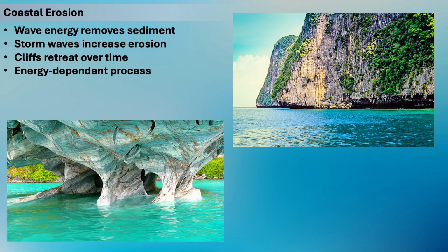Storm waves are especially important. During storms, wave height and period increase. Longer period waves carry more energy and penetrate deeper into shallow water before breaking. Storm surge can also elevate water levels, allowing waves to reach portions of the shoreline that would normally be out of reach.